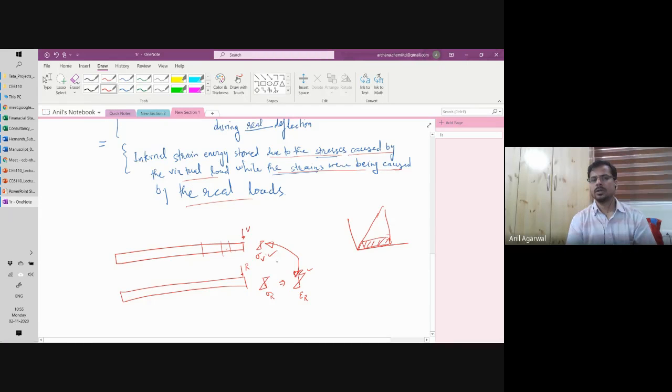Fine. So for some cases it could be basically strain multiplied by stress. Sometimes it can be internal forces multiplied by internal displacements. Sometimes it can be moment multiplied by curvature. So for a truss, it will be force and displacement. For a beam, it will be moment and curvature. You can say this is the moment that is produced, and this is the curvature that is produced.